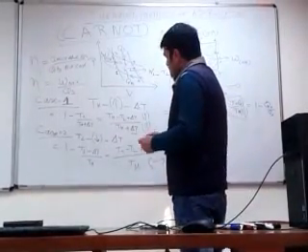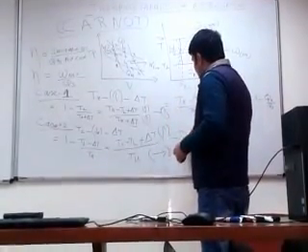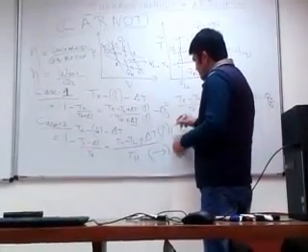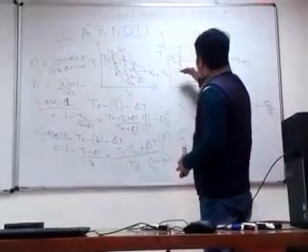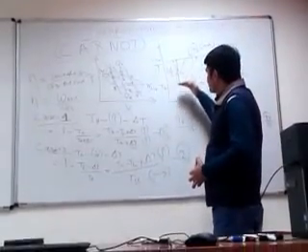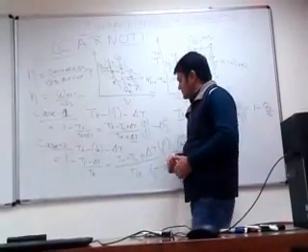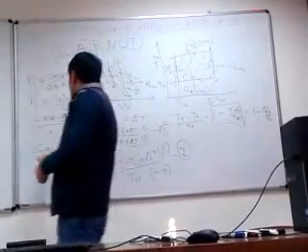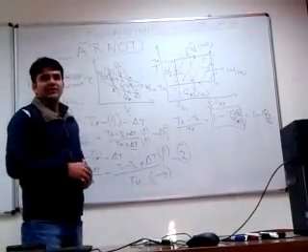So by seeing case number 1 and case number 2, I will decrease the lower temperature to increase the efficiency of the cycle. So case 2, lowering the lower temperature, is the best way to increase the efficiency.